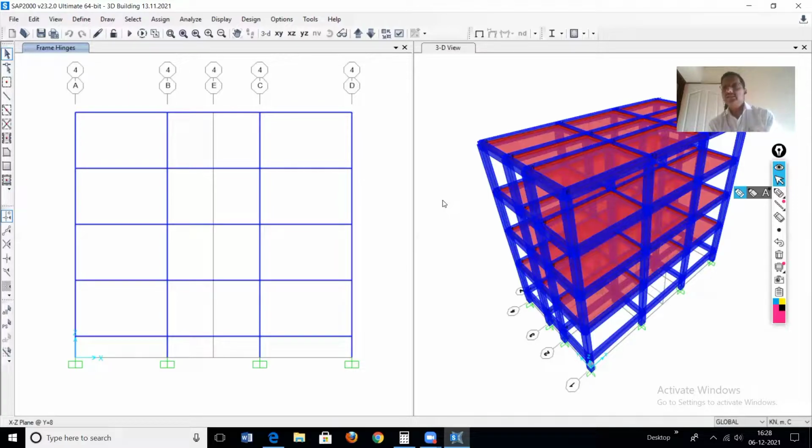So the ends are very critical. At the ends, under lateral loading, the flexural stresses as well as shear stresses are maximum. Therefore these are critical locations for failure under earthquake, and so the material nonlinearity is assigned at the ends only. Now to assign the material nonlinearity at the ends, this is called the lumped plasticity approach. So we have to assign some plastic hinges.